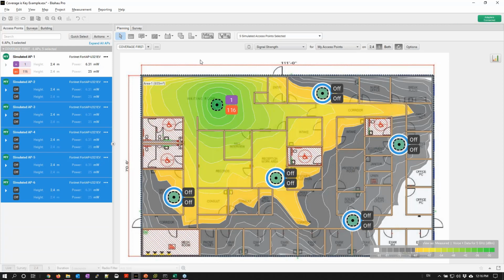We've still got, you know, not a bad connection, but obviously everything in these fringes is outside of the bounds of a good connection. So if we're having a look at that in itself, we can adjust. This is set to a voice network. So if we went up to -70, as we can see, we only get a little bit more of a fringe. And I'm showing you this as well for another reason: you can design Wi-Fi very well in Ekahau, but if you're trying to be dodgy, you can also make it look a hell of a lot better than it should.